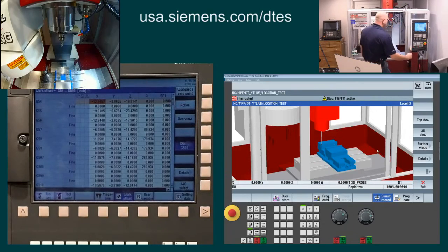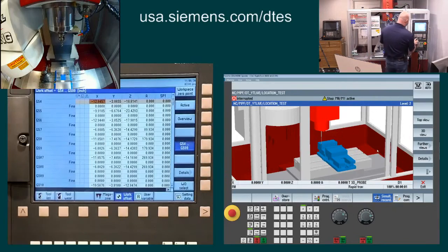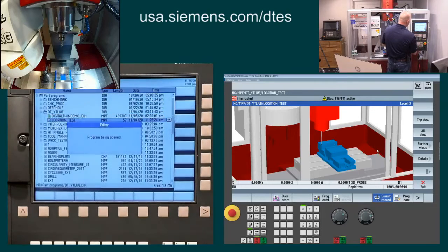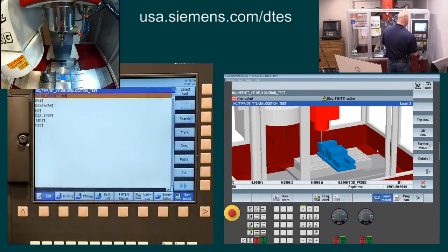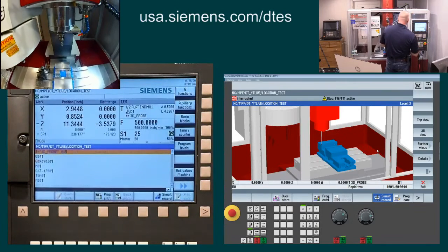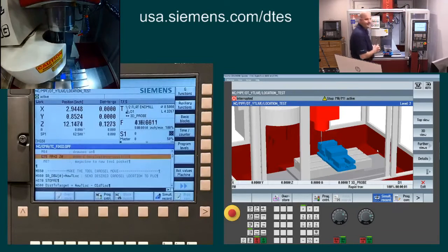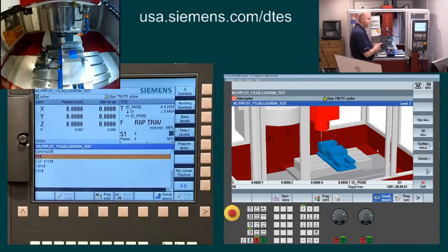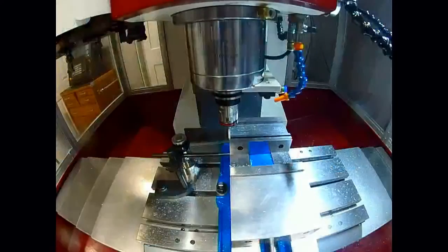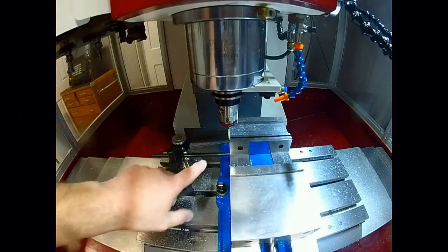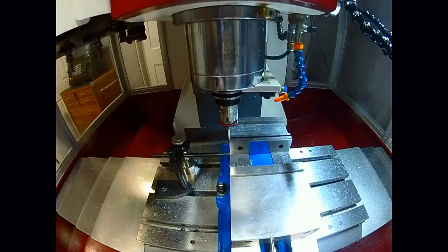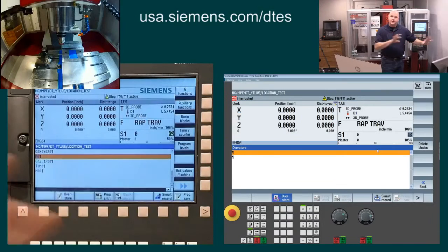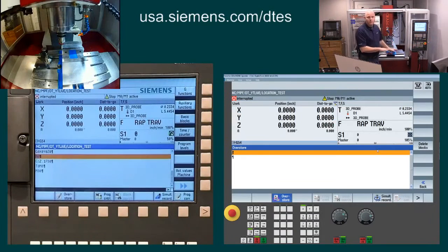Well, boy, I hope so. So here we're going to jump over, get into our program. I've built the exact same program here on my machine tool, doing the same move. We're going to load up our probe, and now I'm going to position down to the corner of my vise. So to give you guys the close-up view, and certainly it's hard to see, I'm sure, but we are right there at the corner of my vise. So validating that my spatial representation of this machine tool is the same between my physical realm and my virtual world.